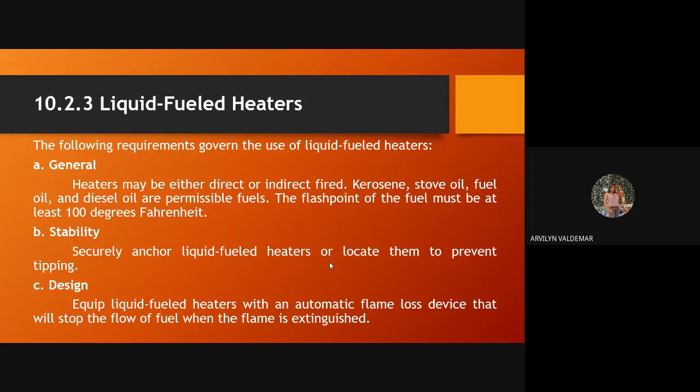First, general. Heaters may be either direct or indirect fired. Kerosene, stove oil, fuel oil, and diesel oil are permissible fuels. The flash point of the fuel must be at least 100 degrees Fahrenheit. Stability: securely anchor liquid fuel heaters or locate them to prevent tipping.